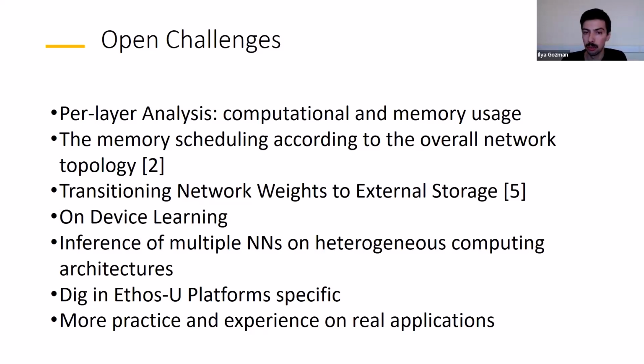With our understanding of the intricacies of contemporary neural network architectures, we have laid out plans to efficiently manage memory. Our upcoming strategies involve transitioning the extensive network weights to external memory. We believe that this will optimize the inference process and streamline our fine-tuning approach. The idea is to dynamically swap chunks of network weights between the device's SRAM and external flash storage. This allows for the deployment of large and complex neural networks without compromising on accuracy.